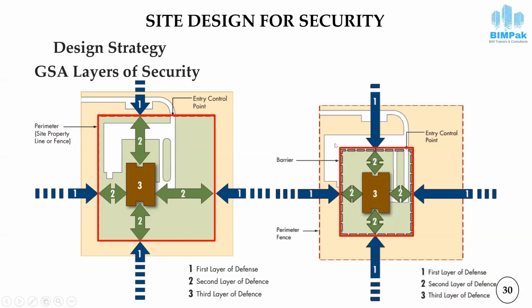So both have merits and demerits. In this case, we have a higher standoff distance as compared to the other position. But at the same time, in this case, your vehicles are also secured. While in the second case, your parking is outside the safe zone, so your vehicles will not be safe. Somebody can attach some magnetic bomb or some IEDs or VBIEDs to your vehicles. So you have to consider both these factors in your design strategy.